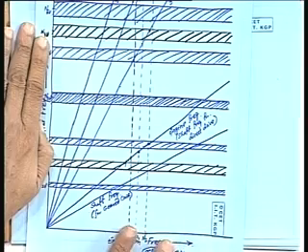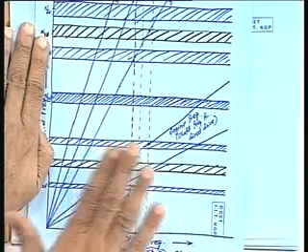Okay, we assume that as per the classification societies and the usual shipbuilding practice, you are trying to design your structure and then these are the estimated frequencies. But this has nothing to do with the excitation. If you do something with the mass distribution of the exciter, then the excitation frequency will be different. If you say that instead of N1 it may generate N2 or N3 or something like that, but that is an excitation, nothing is happening here.